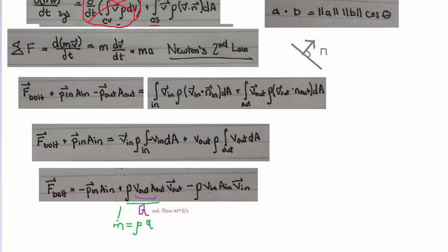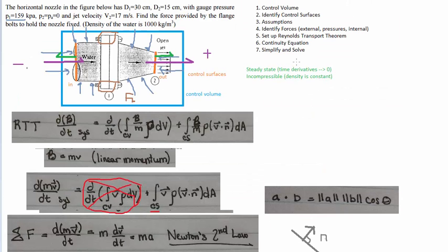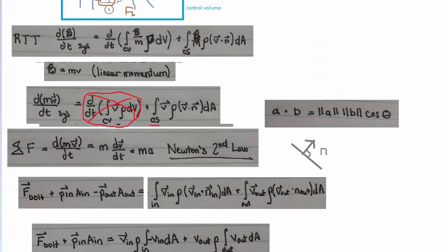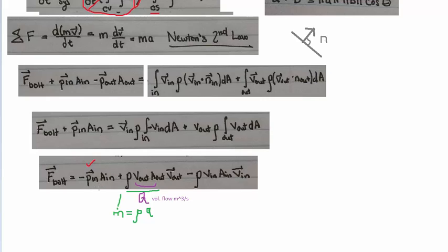So it's mv, literally your change in momentum due to the fluid moving through the system at that surface. Okay, so how do we actually get to solving this problem? We're looking for this. We're told the inlet pressure. We have the diameter at the inlet, so that's going to tell us the area here. Remember that this picture we're looking at is a cross-section. It's an oversimplification of the geometry. This inlet is really circular, and this outlet is circular, and the entire pipe is cylindrical.